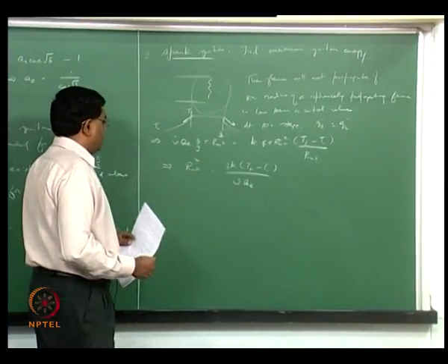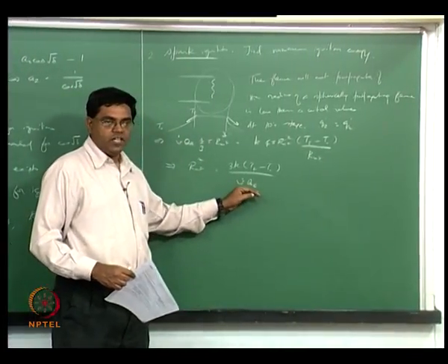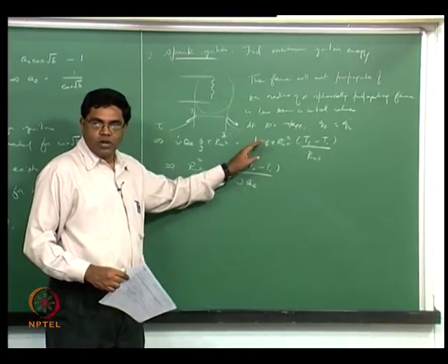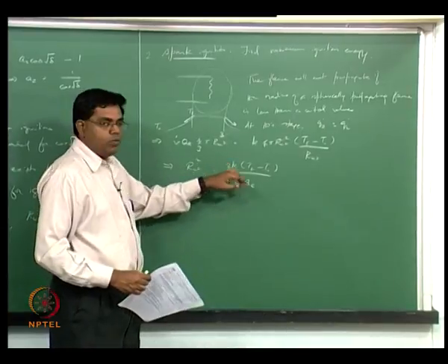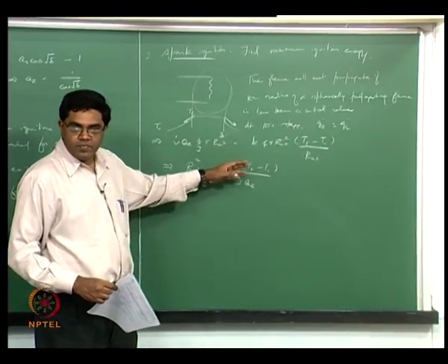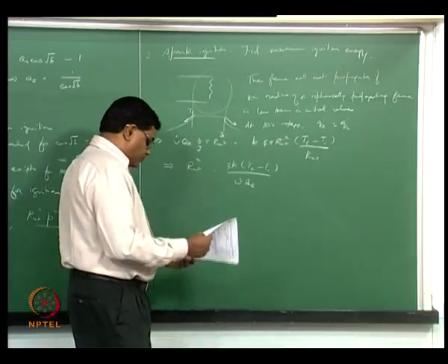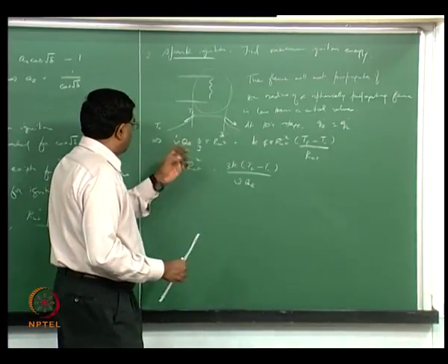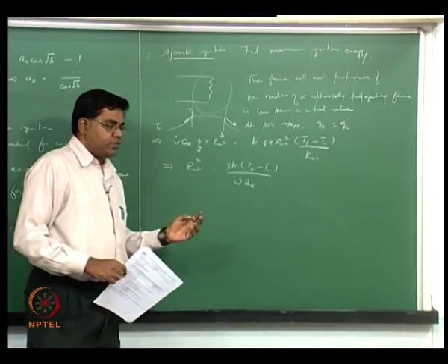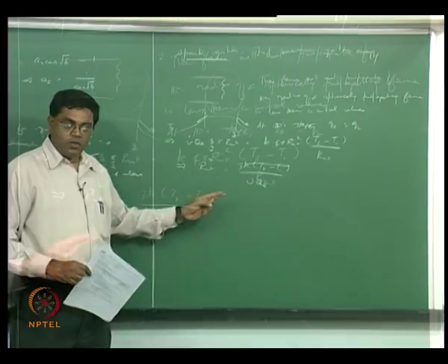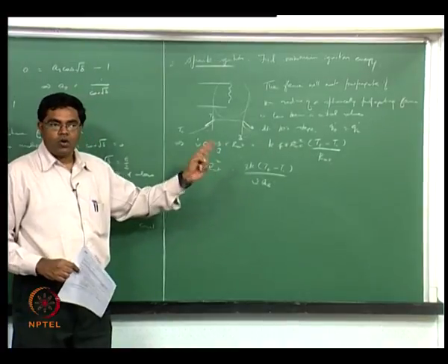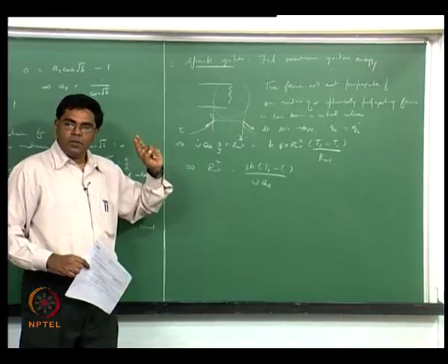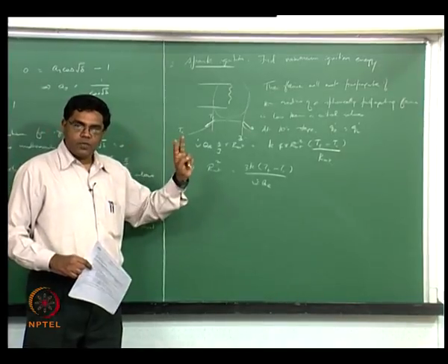And previously we also said that this Q_R is nothing but Cp times (Tf minus T naught), so we don't have to worry about the Tf minus T naught, but keep the Cp at the bottom. And if you now have a k over Cp, that can be directly written in terms of alpha, right. So you now find r crit squared is equal to alpha divided by W dot. Similarly, we also had S_L is equal to square root of alpha W dot, or S_L squared is alpha W dot, right.